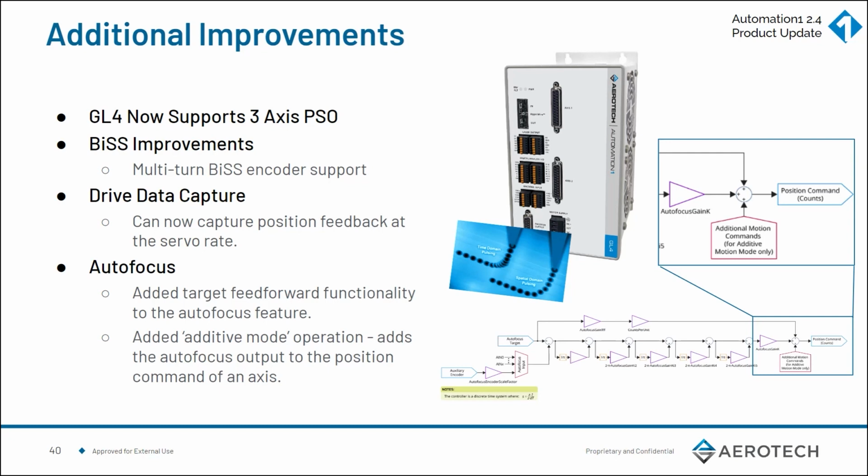This is not trying to follow a fixed velocity or maintaining constant velocity in your motion to obtain equal pulse spacing. This is actually counting encoder pulses, doing a vector calculation on those pulses, and using that vector math to actually maintain spacing. It's a very direct, very well-known in laser industry and very successful method of controlling spot-to-spot placement of industrial lasers. So if you're not familiar with PSO already, please reach out to your local sales guy. This is something you probably want to know about.